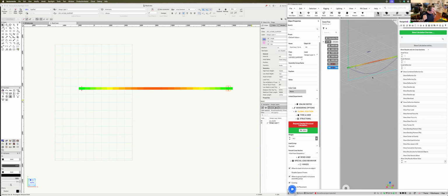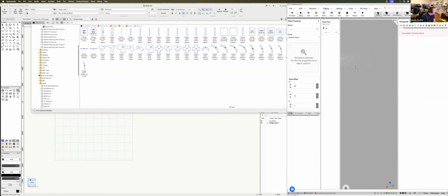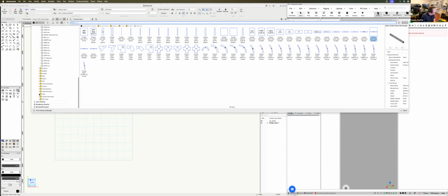Note that these deflection limits in the European unit are based on specific applications, and the load tables that the truss manufacturers prepare do not include them. So depending on the load case, the allowable deflection is different. This put a lot of pressure on the American truss manufacturers because by default, American trusses actually do use the deflection limit. So if I'm using some American truss in here,